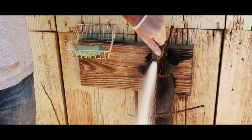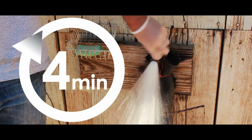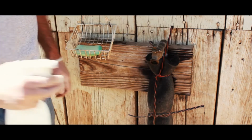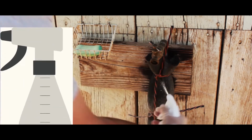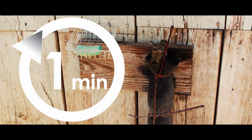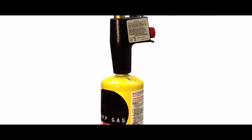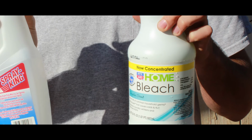If you are collecting from a spigot or shunt valve, turn on the water to the highest possible flow for 4 minutes and then turn it off. Wipe the inside of the spigot or valve opening with a 10% bleach solution and let it sit for 1 minute before collecting the sample. Your lab may recommend other methods for sanitizing like flame torching or chemical washing, but bleaching is acceptable.